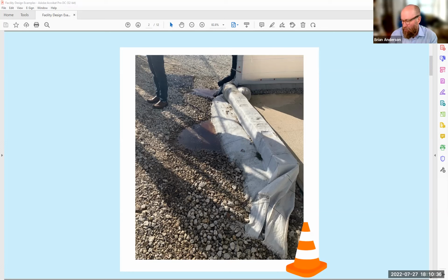So in facility design, and to protect from biological, chemical, and physical contaminants, site design is really important, and how the building sheds water, where that water goes. Standing water, mosquitoes breed in standing water, microbial contamination breeds in standing water. Somebody's going to step in that at some point and have that on their shoes as they come into a facility.